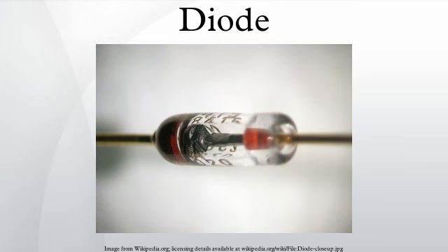The first LEDs were red and yellow, and higher frequency diodes have been developed over time. All LEDs produce incoherent, narrow-spectrum light. White LEDs are actually combinations of 3 LEDs of a different color, or a blue LED with a yellow scintillator coating. LEDs can also be used as low-efficiency photodiodes in signal applications. An LED may be paired with a photodiode or phototransistor in the same package, to form an opto-isolator.